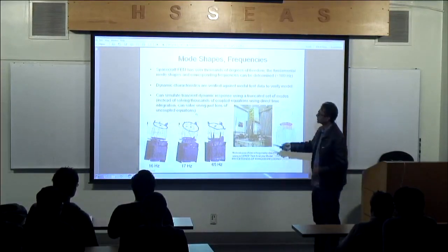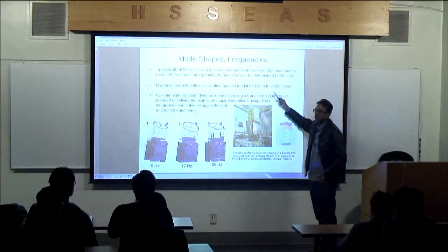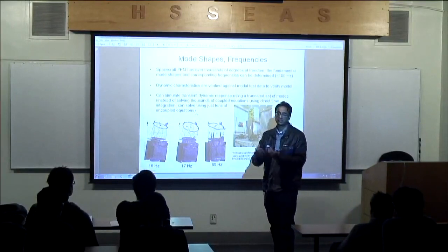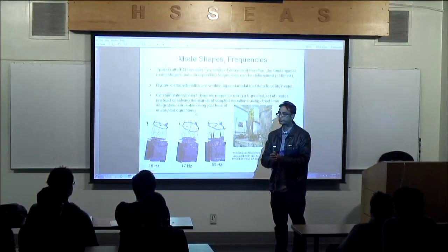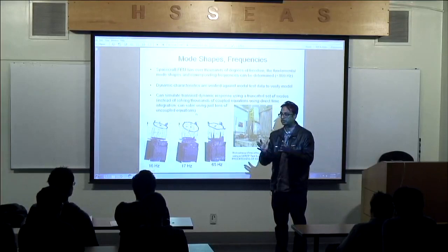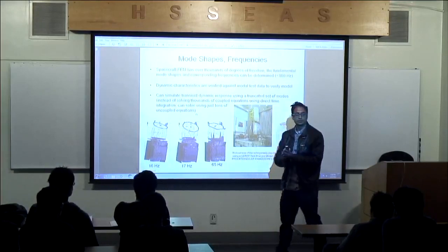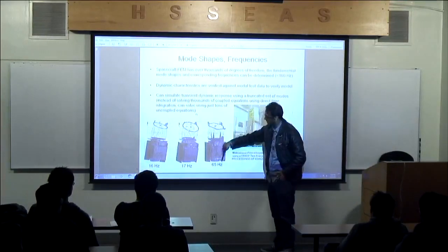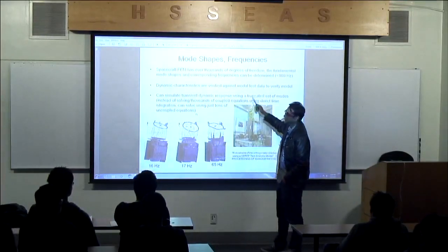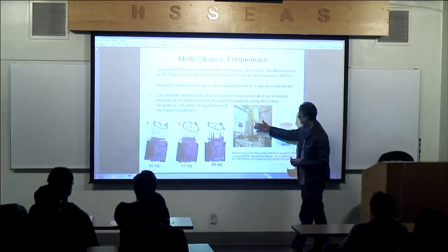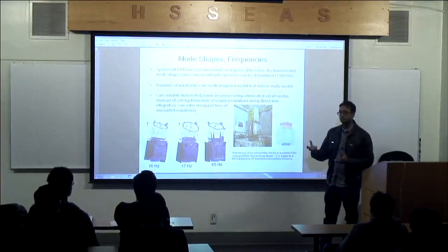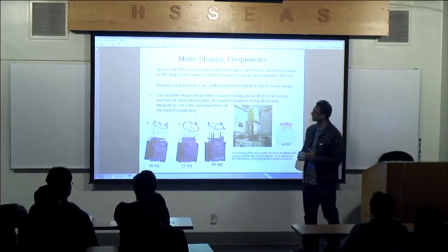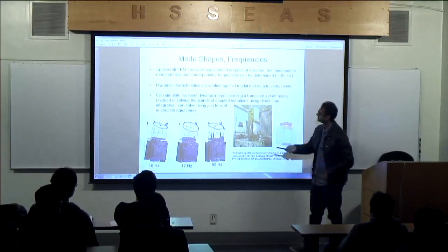And in this paper, they actually determined all the modes below 100 hertz because they felt that in actual application, the spacecraft will not see, they don't expect forcing functions with frequency contents greater than 100 hertz. That's what they felt, and they talked about. So the dynamic characteristics here, these values were checked against tests. They actually did some testing on the spacecraft, and they vibrated the structure, they have accelerometers to basically verify the models. I'll talk about that in a couple of minutes.